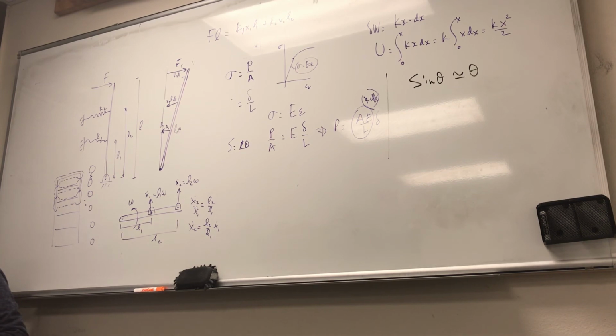See, x dot 2 is L2 over L1 x dot 1. x dot 3 is L3 over L1 x dot 1. Why are we doing everything in terms of x dot 1? Because that's the equivalent. When we write this equation, x dot 1, x dot 2, x dot 3, everything is about x dot 1, and on the right hand side you have x dot 1, so it cancels out.